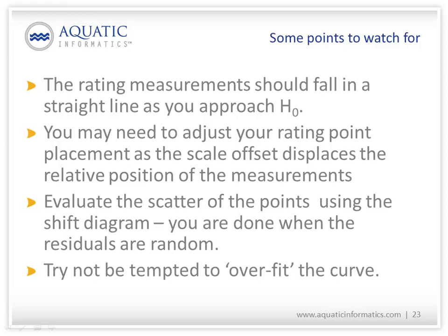And the more time goes on between when a measurement was taken and the control conditions that you're trying to evaluate for, the more you can expect that those older measurements are going to plot further away from the current rating curve.